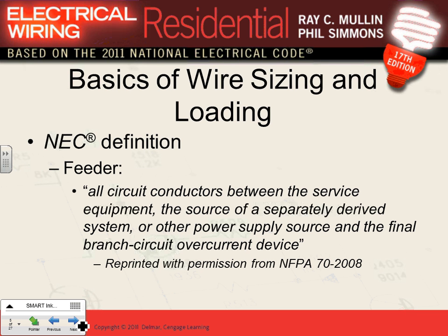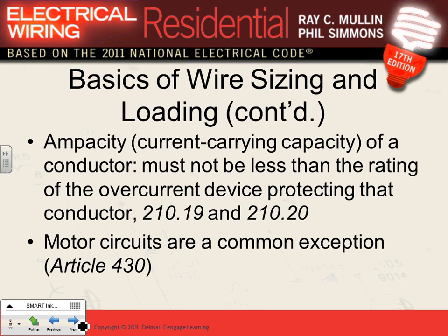Here's the feeder. The feeder is defined basically as conductors between two panels. That's your feeder as we draw them. These are the most important things, guys, you have to keep in mind when you size your conductors. Now we know what the feeders are and what the branch circuit is. Another thing, guys, is that the ampacity of the conductors cannot exceed the overcurrent protection device that protects it. Based on the NEC code book, the service entrance conductors, the feeders and the branch circuits are all conductors. They need to be protected based on their ampacity.